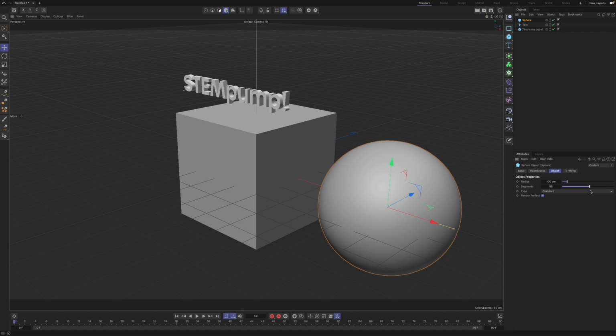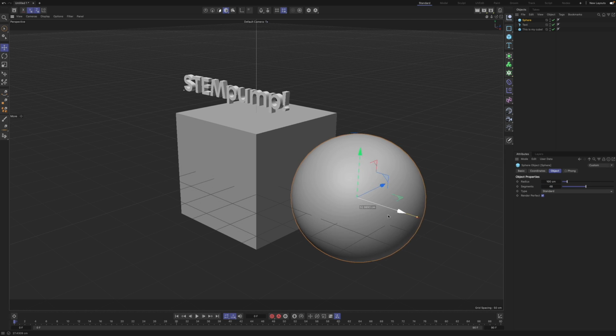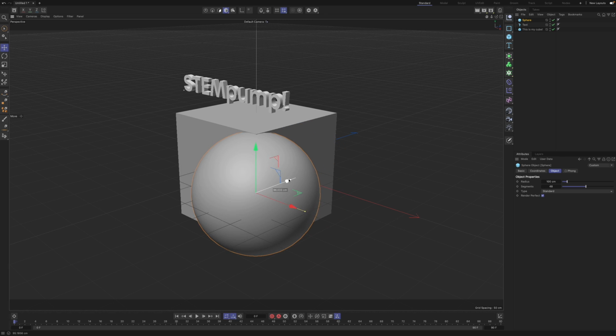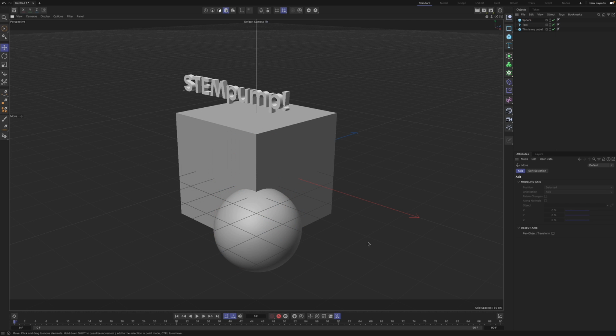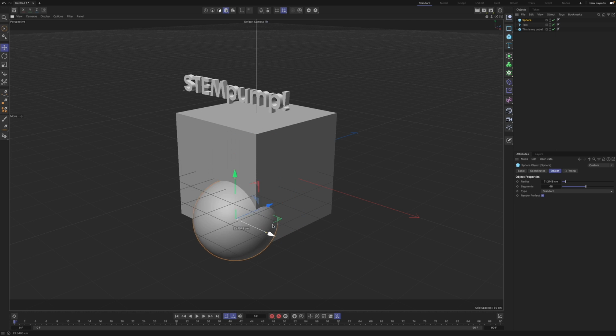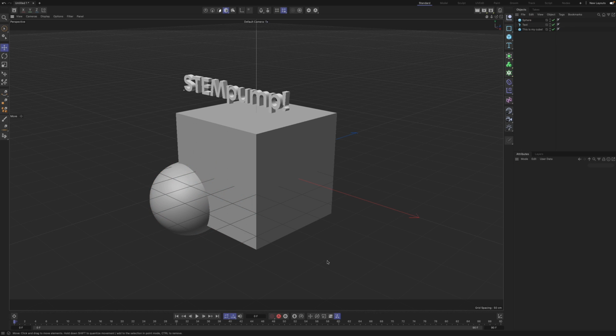So I usually go around 32. You can see 32 still has a little bit of ridging here and there. You can do 48, and I can even just move this inside here. Maybe I'll just do that. I'll press T to scale it. Use E to move it just downwards, maybe. Just lock it inside there. We can just leave it to the back. Making Kirby in this is very easy.